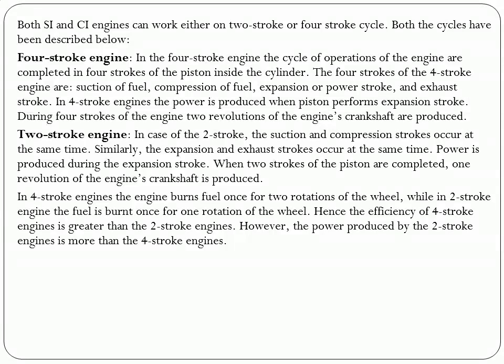Four-stroke engine. In the four-stroke engine, the cycle of operation of the engine is completed in four strokes of the piston inside the cylinder. The four strokes of the four-stroke engine are suction of fuel, compression of fuel, expansion or power stroke, and exhaust stroke. In 4-stroke engine, the power is produced when piston performs expansion stroke. During 4 strokes of the engine, 2 revolutions of engine crankshaft are produced.